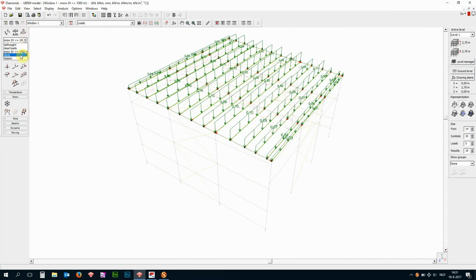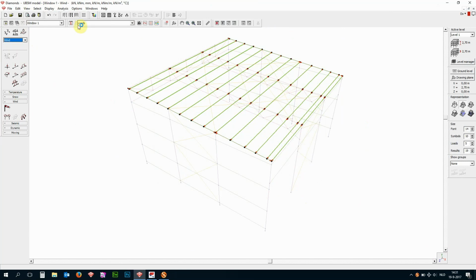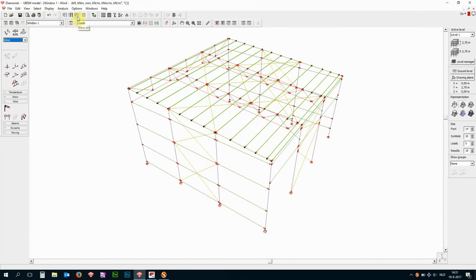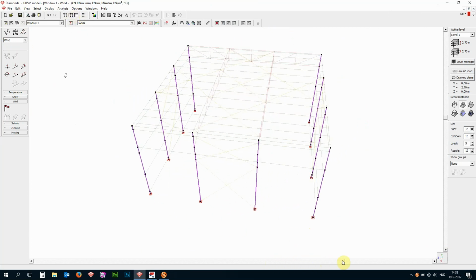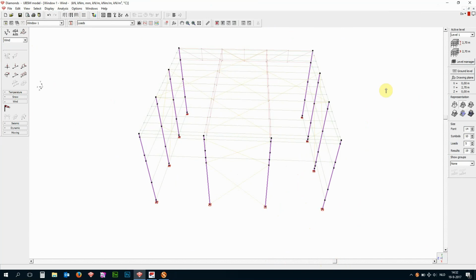We move on to the wind load case, and I'm going to show the whole model again, and we are going to add some wind loads on the columns only. So I'm going to keep the control button down and click once on the columns and keep only these elements visible, and we will define a wind load going from right to left. So selecting all these elements, and I'm going to use the surface load generator again.